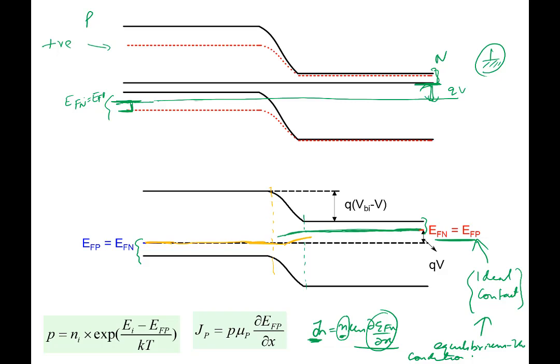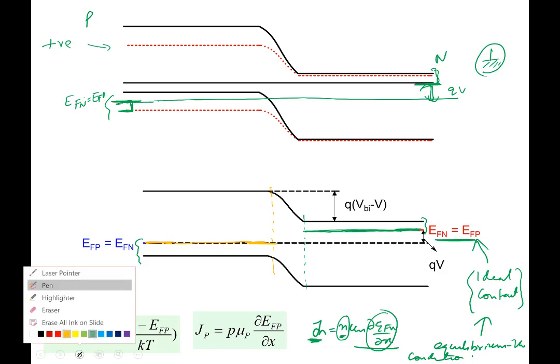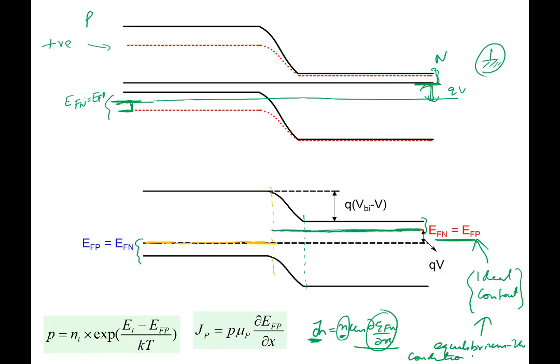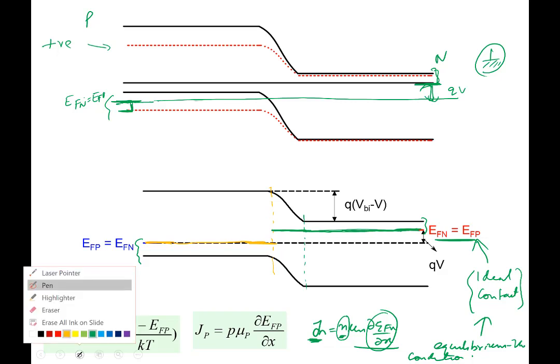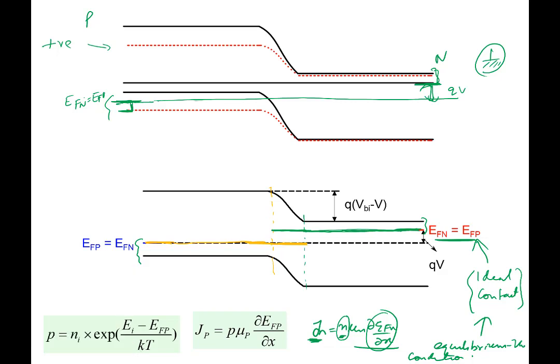Although it will start to change, remember how thin the depletion region is. Depletion region is actually quite thin, maybe hundreds of angstrom. And we are forward biasing it, so the depletion region even becomes smaller. So it's a reasonable assumption that even though a gradient may be there, I could say this is almost constant till here, because the depletion region is very narrow. Yes, n is actually going down, but the depletion region is very narrow. Similarly, this is also constant in that narrow region.